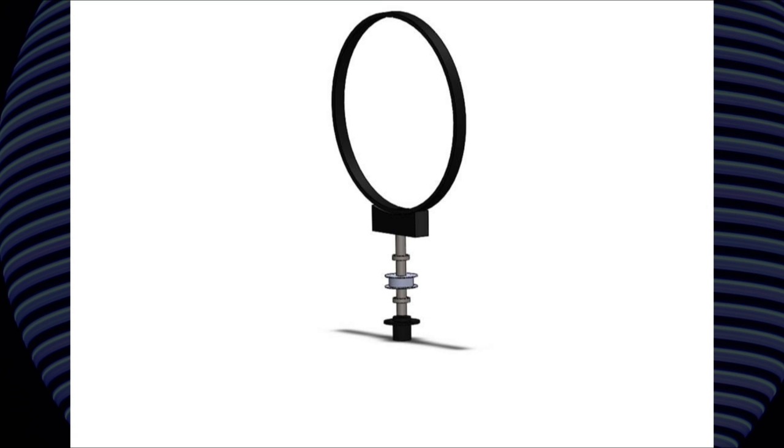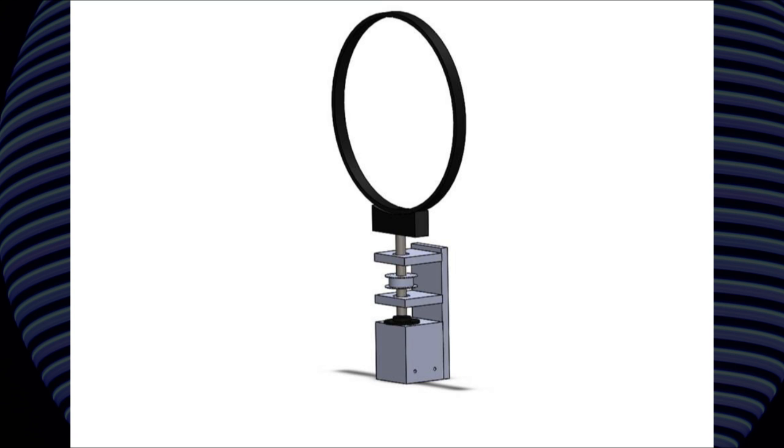To stabilize the rotation axis, we added 2 ball bearings. To rotate the axis, we added a pulley, which is connected to a motor with a driving belt. You can see here the complete structure of this part of the globe.